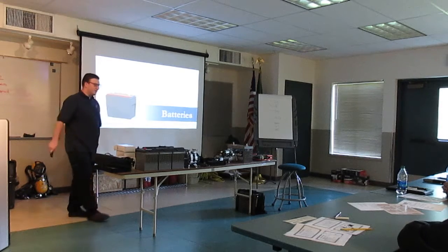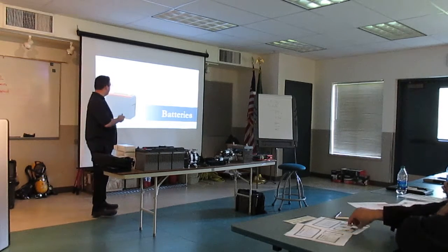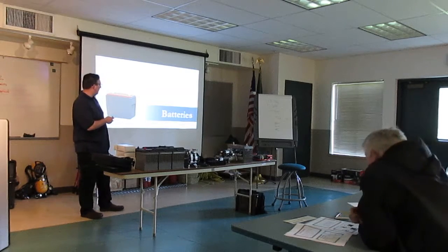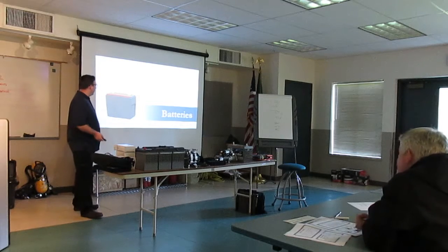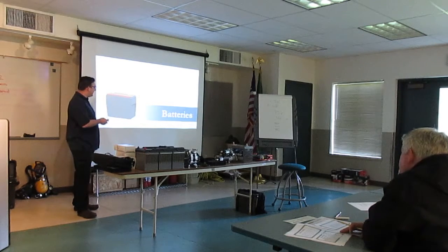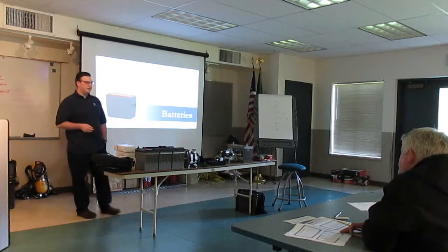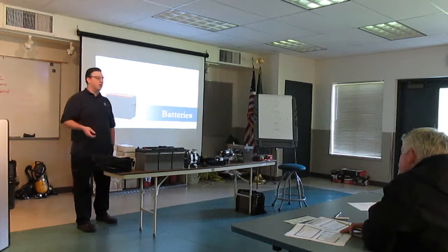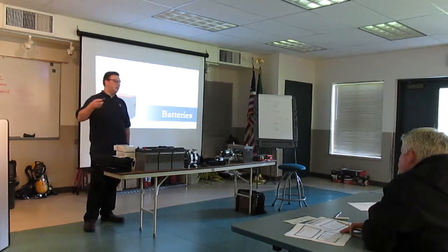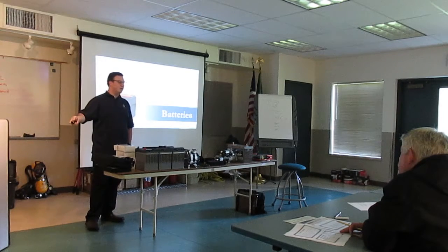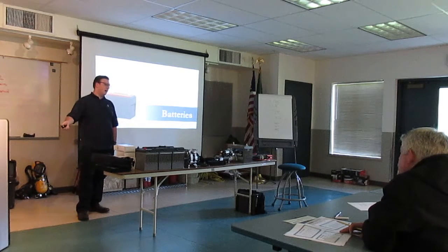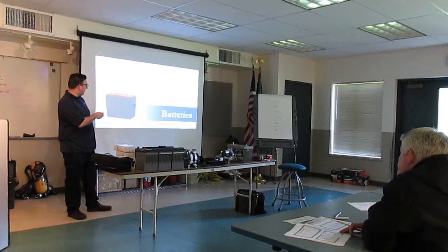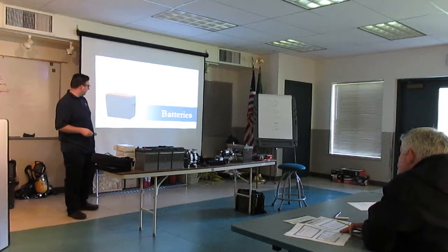Now, our batteries, as I said this morning, are used to store electrical energy and provide high current for starting. That's their job. They also supply power when demand exceeds alternator output. This is a fun one to figure out if your system's overloaded. You wonder why you had a vehicle come in with dead batteries, you check the charging system, everything checks out fine, but you're still having issues. Your battery supplied that voltage to get the system going.